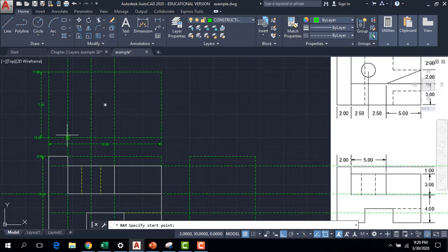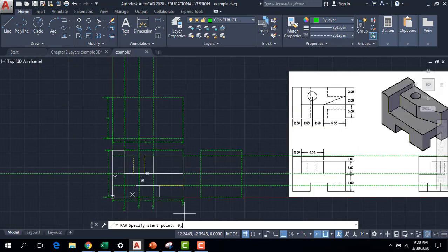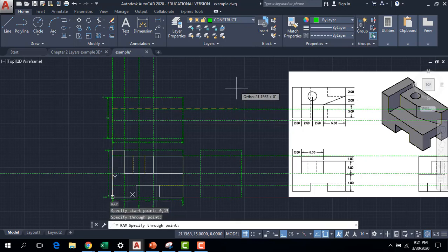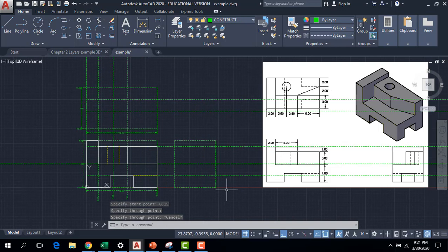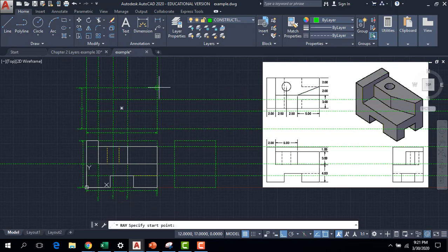Let me show you another trick. This is called a miter line or a folding line. And it's how you can kind of connect the top view to the lower right-hand view. And that is, we're going to extend the lines of both of these guys, and after that connect the corners.